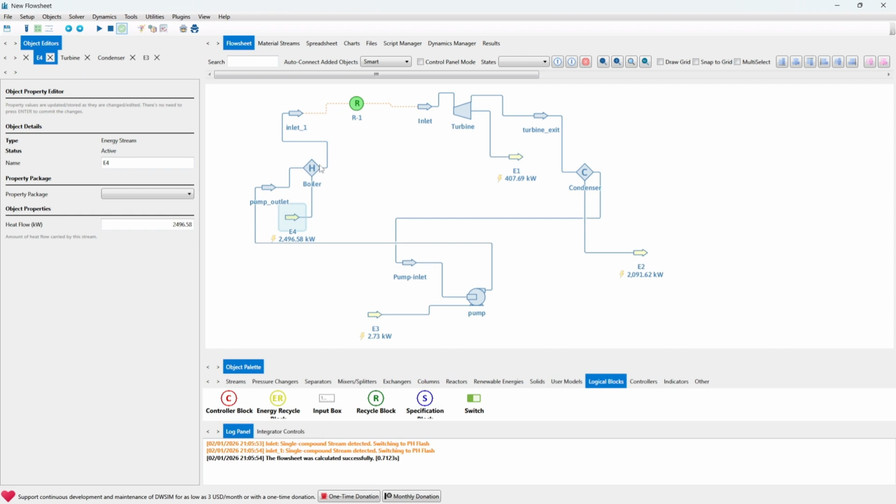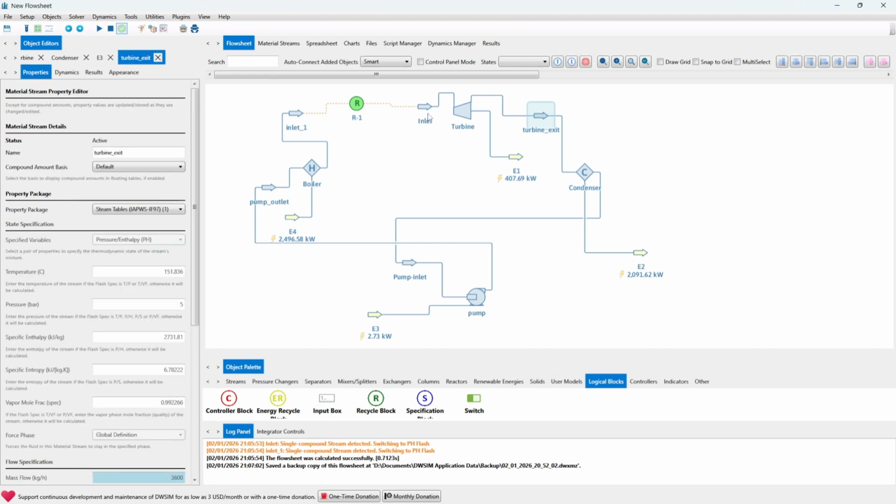Let me discuss some things over here. For the condenser, the heat rejected from the condenser is the latent heat of vaporization. In this case, since we're condensing the fluid, it's the same thing, but now it's the latent heat of vaporization. Why? Because we're changing phase. As you can remember, let's select this turbine over here.